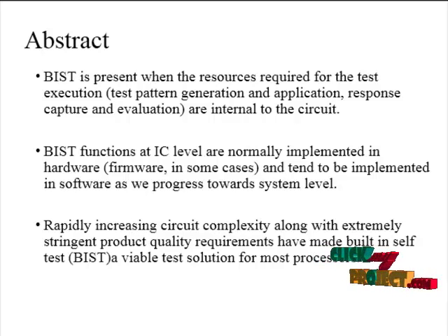remain undetected. Although logic bugs are possible to detect in pre-silicon, with increase in design complexity, shortened design time and complex OS and software demands, this can lead to escalations of bug escapes. A modern microprocessor design can experience considerable design bugs, specifically in memory interfaces. Controllability and observability are key attributes in any post-silicon validation methodology.